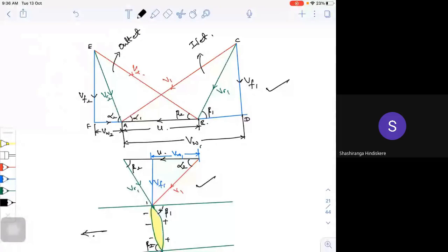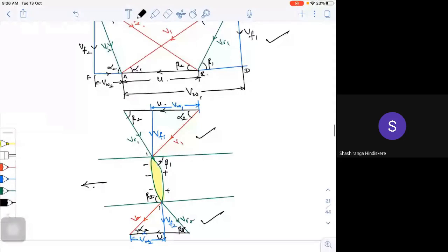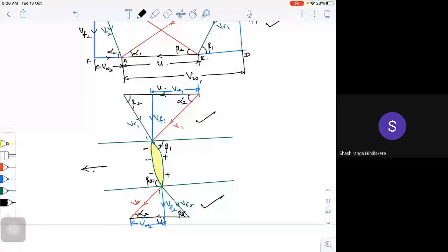Now to solve it, I am going to use the trigonometric principles. Let us consider the inlet velocity triangle. It's very similar to your previous problem. We are supposed to find beta 1, beta 2, your power, and the extra thing we have is axial thrust. I know the value of alpha, which is 18 degrees. I know the value of V1. This is my alpha 1 and beta 1.